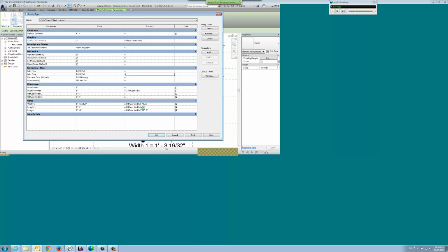Okay, you can even group it so that it's for fittings or air terminals or mechanical equipment, whatever you want. But copy-paste the formula into the Excel sheet, and in the cell right next to it, just give a brief description of what it does. This is pretty straightforward, but if you haven't done this parameter in 3 months, you might forget which one it is. You might be saying, oh, do I need a not? Do I need parentheses? Do I have that? Certain things I can go in there and start trying and get results I don't expect.